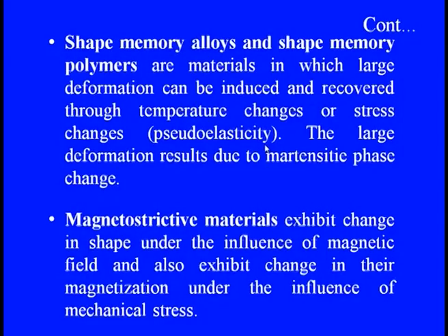Then we have the magnetostrictive materials, which can exhibit a change in shape under the influence of a magnetic field, and also can exhibit a change in their magnetized properties under the influence of mechanical stresses. Through that, the sensing and the actuation features can be coupled together.